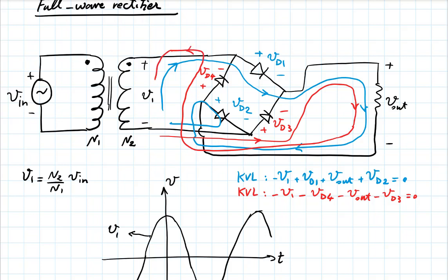You see? Going down like this. So you see that the two other diodes are being used in the negative half, but the current is going still in the same direction in the load, in the output. And that's the beauty. That's what this circuit is accomplishing.